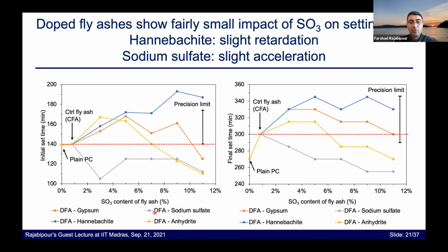On the other hand, if you look at sodium sulfate, by adding sodium sulfate, the time of setting tends to decrease or gets accelerated, both the initial as well as the final. For the other two, which represent gypsum addition or anhydrite addition, the effect is mixed. At low dosages, we have some retardation. At higher dosages, we have some acceleration of the setting.